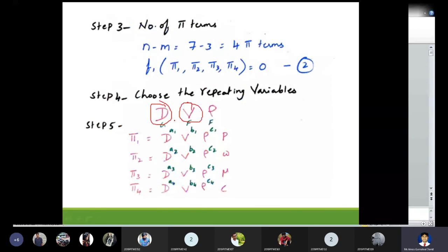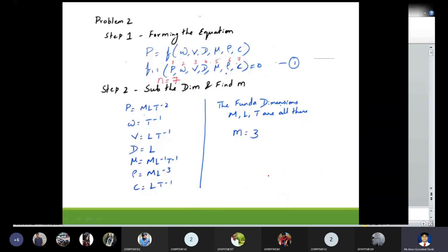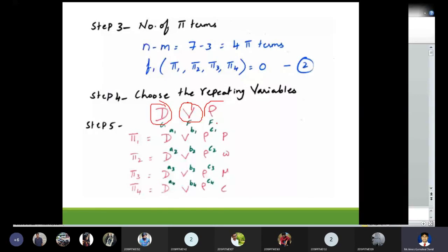Now next is fluid property. As I said, for fluid property the preference is rho, then mu. There is rho, there is mu. Clear? But which one should I give preference to? I should give preference to rho. So I've given the fluid property status to rho. Now I have declared the status of all these repeating variables.